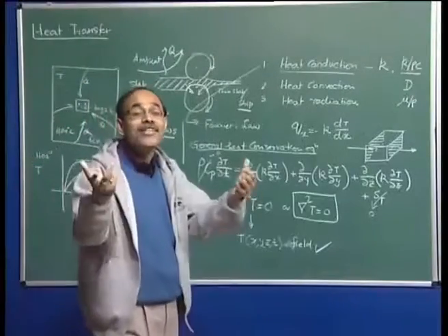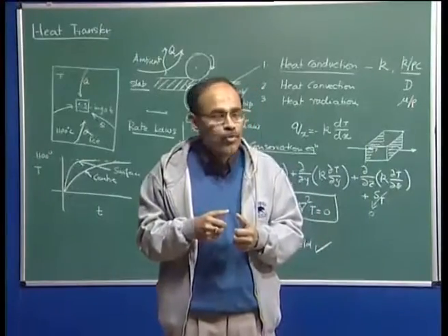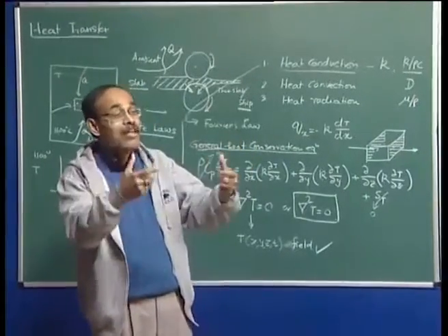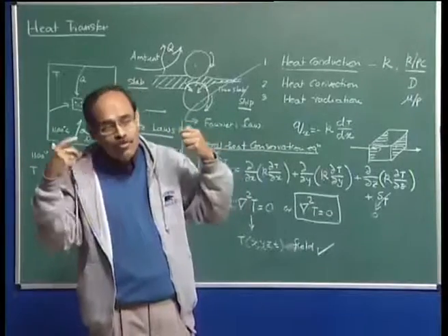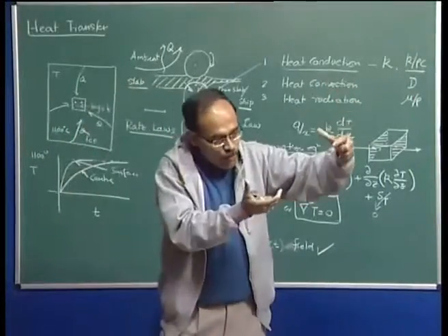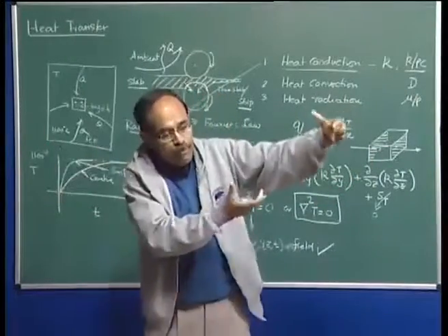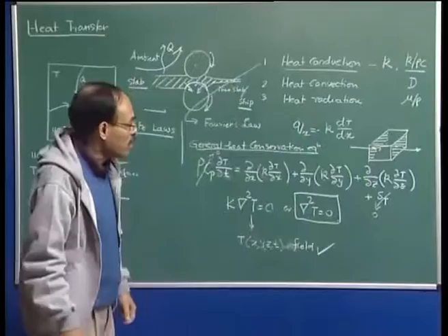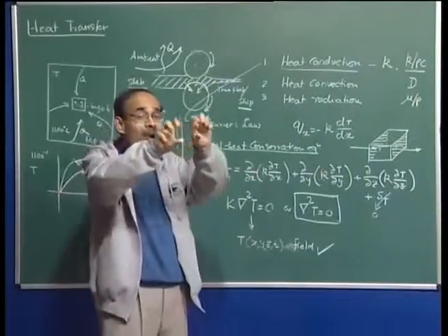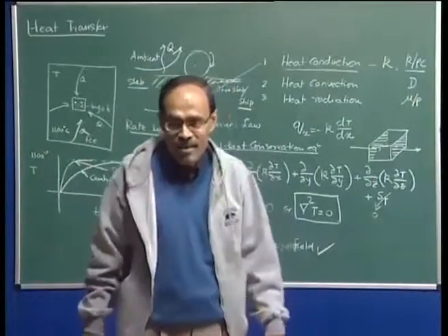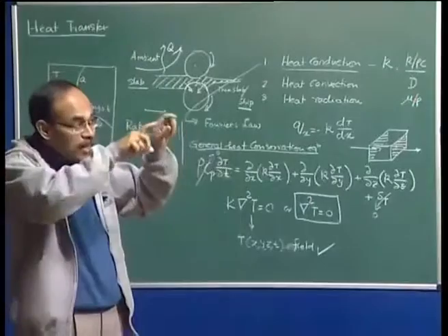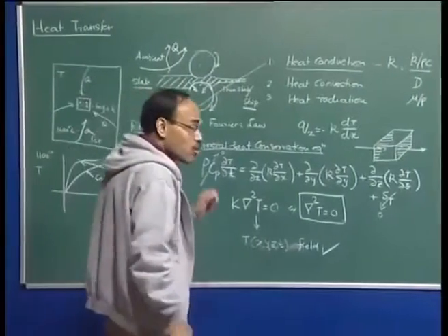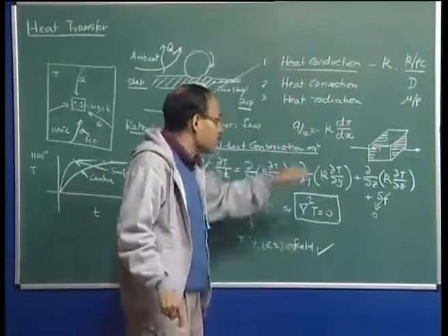On the other hand, imagine in a winter night you have put a convection heater in your room to warm you up. The moment you put the switch on, and the fan as well as the heater in the blower goes on, you will feel that the heat is immediately coming to you, and therefore, we conclude that the flow of heat assisted by fluid motion, which is the fan throwing the heat into the room, is much more rapid than conduction heat or radiation heat. Also, you can imagine a usual old fashioned type room heater with rods. Heat flows from the surface of the coils to the ambient not because of conduction, not convection, but because of radiation, which is the third mechanism which I am going to discuss.